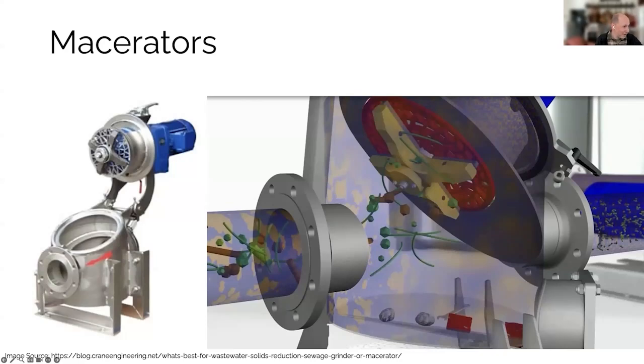You've got effluent coming in from the left, going through those blades, which are spinning around on that grate. They're self-sharpening. You've got a bucket or a space at the bottom, a trap, where larger materials will fall so that the machine doesn't get jammed up. And what comes out the other side is finely cut small bits.